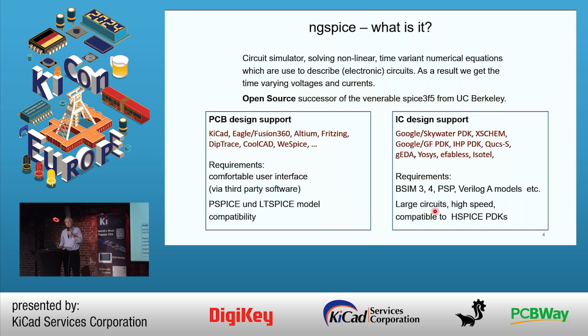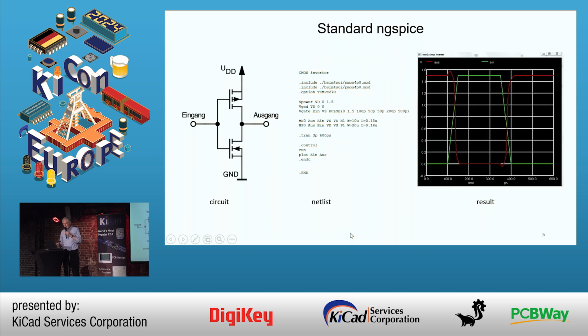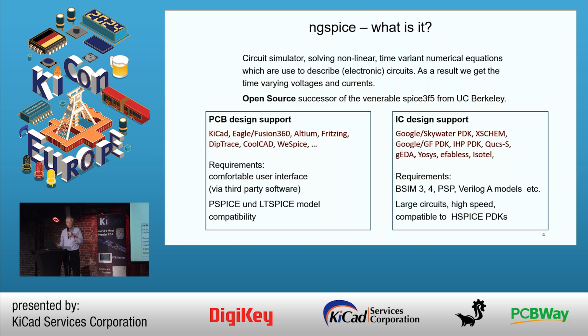Well, we need to have a comfortable user interface, and you will see, unfortunately, that ngspice itself doesn't offer that, so we rely on third parties. We rely on KiCad, for example. We have to be compatible with PSpice and LTSpice, the other famous simulators, at least concerning the models. So that's what we do. On the other hand, there is IC design support. Integrated circuit development heavily relies on simulation.